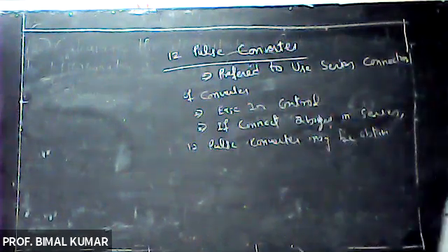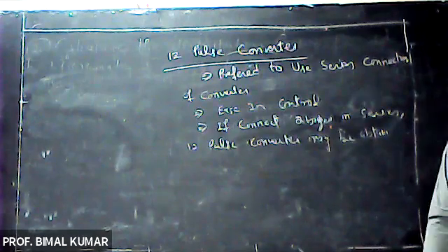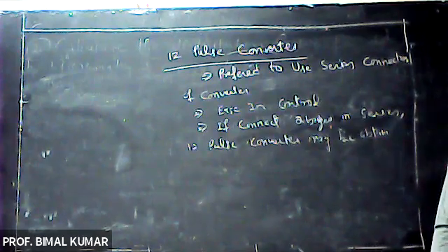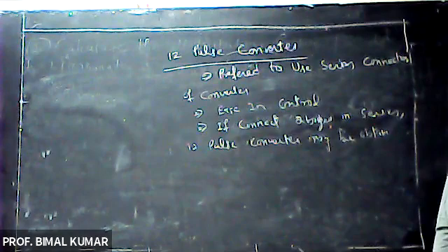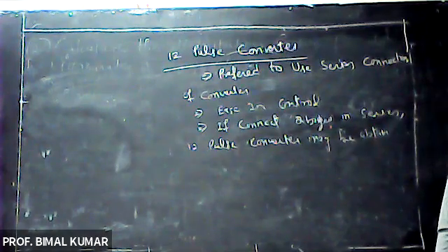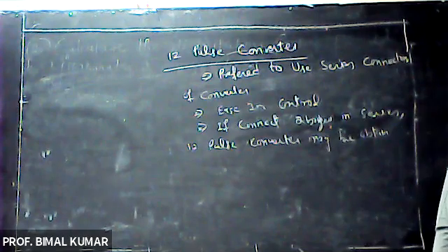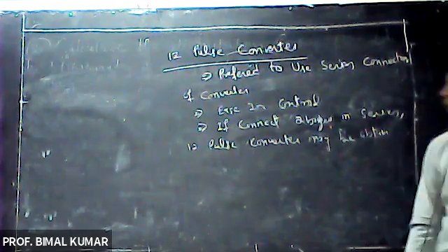And 30-degree phase displacement between the two sets of the source voltage is achieved by the transformer connection: star star for feeding the one bridge and star delta for feeding the second bridge.